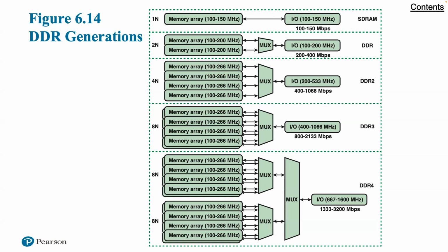Bank groups are separate entities such that they allow a column cycle to complete within a bank group, but that column cycle does not impact what is happening in other bank groups. Thus, the true prefetch of 8 can be operated in parallel in the 2 bank groups. This arrangement keeps the prefetch buffer size the same as DDR3 while increasing performance as if the prefetch is larger. So in this figure, it shows a configuration with up to 2 bank groups. With DDR4, up to 4 bank groups can be used.